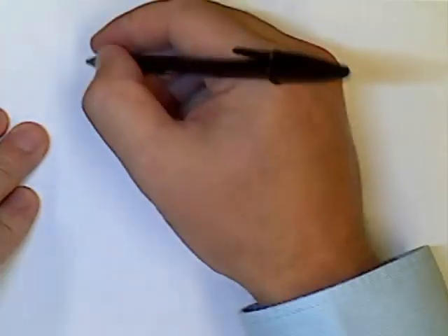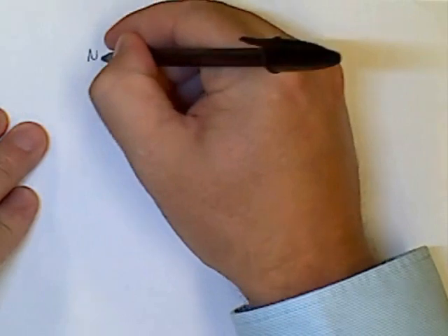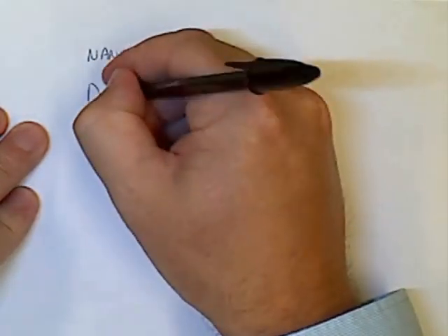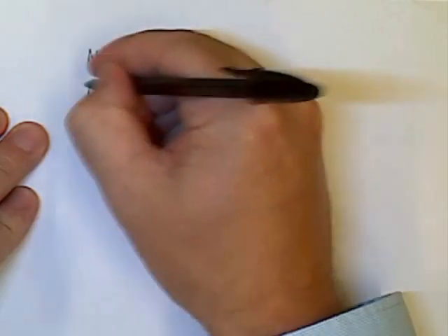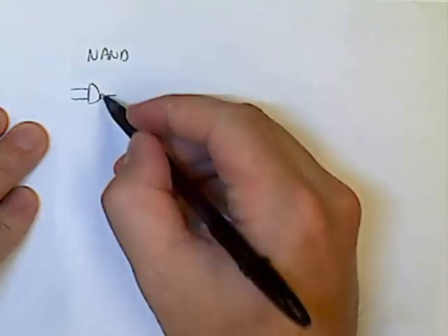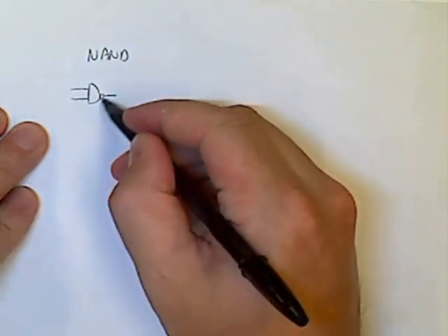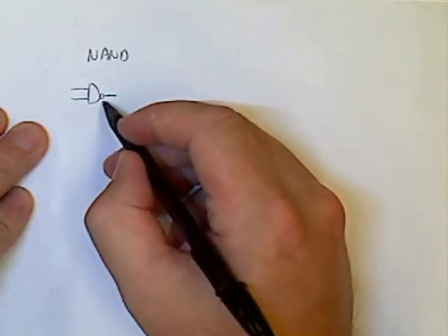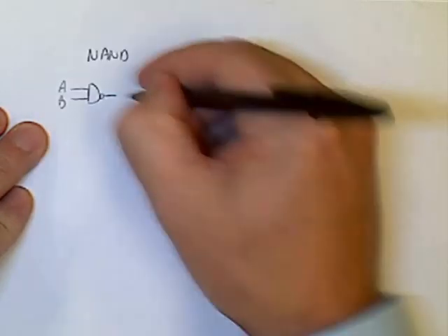And we call that a NAND, and we're giving a NAND gate this symbol. So it looks like a giant D with 2 inputs and a round circle on the output. That indicates that it's negated or inverse AND. And let's label our inputs A, B and Q.